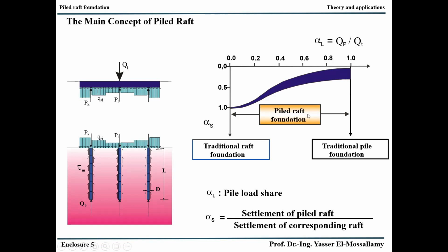Our piled raft foundation is in between, where we assume that the contact between the raft and the direct soil can take part of the load. Of course, this is very logical, and so long as we pour the raft directly on the soil, we can assume that part of the load will be taken directly by the soil. Only in conventional analysis, we don't consider this part of the load.